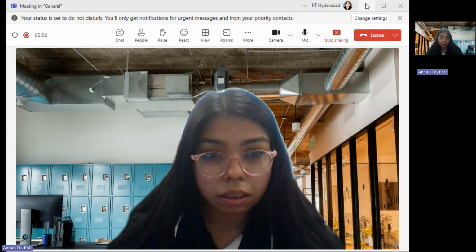So convolution in time. If it is convolution in time, it is a multiplication in the frequency domain, or the Z transform, or the Laplace transform. Convolution in the time domain leads to multiplication in the Z domain. So the ROC is nothing but the intersection of the ROCs of X of z and H of z.